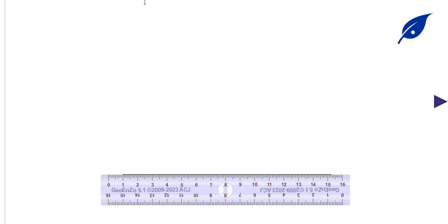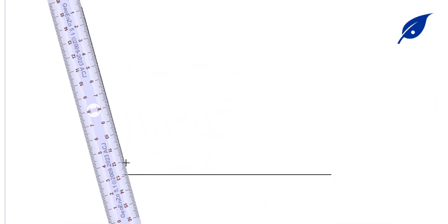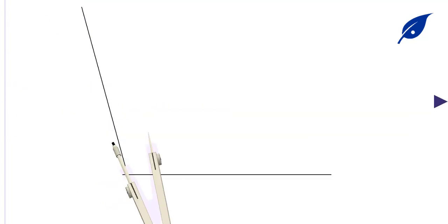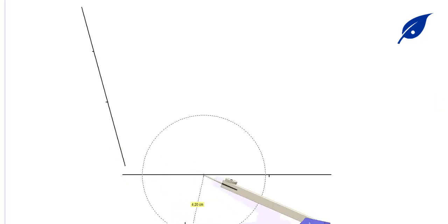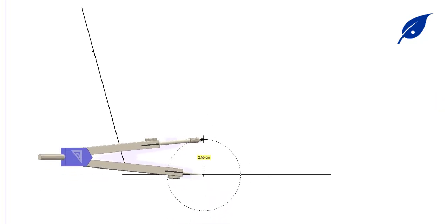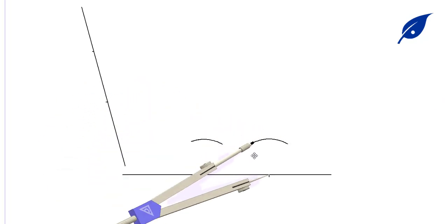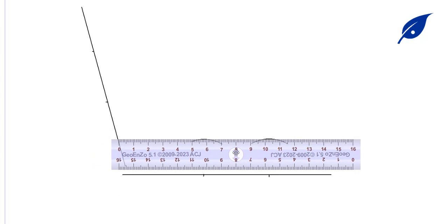In this particular one, we're going to create an arc, but this one is an obtuse angle, as in the lines meet at an angle greater than 90 degrees. The previous one was less than 90 degrees, so we'll repeat the same process. Produce parallel lines here using the arc of 25 millimeter radius to produce this arc.